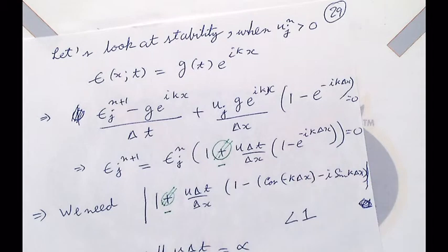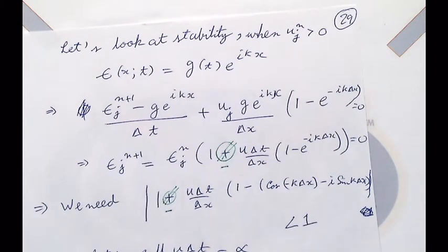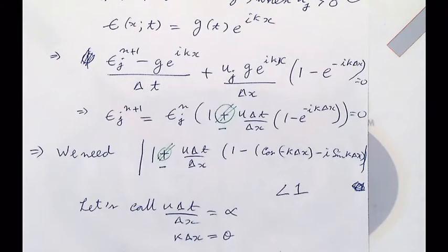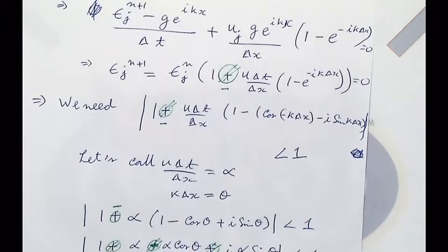When we were talking about advection, there was this concept that we mentioned, upwinding. If you remember, upwinding is basically biasing your derivative towards the direction where information is coming from. I'll leave this up for just a few more seconds so you can fix it. It'll also be on the video, so if you like, you can go back to it.